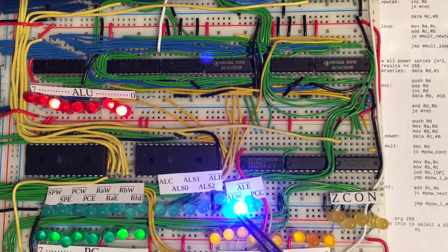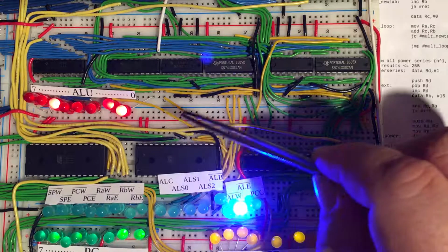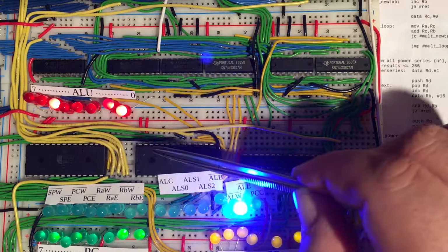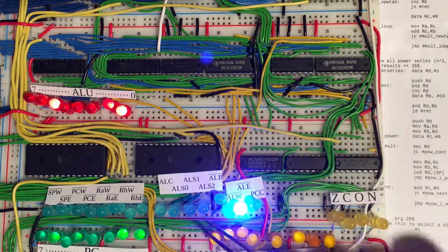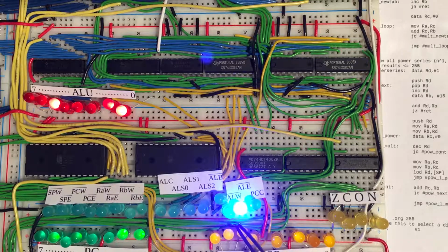And then we have a register which we can use to latch the result of the calculation, and the main reason for that is we can't output the contents of the calculation directly back onto the bus while we are still reading in one of the operands from the bus, and so we have a latch, let's say, on the way. And so it's a 2-step process whereby we first write into that register and then we read from it.